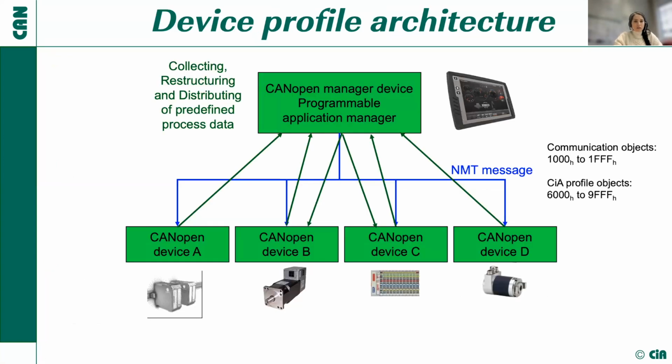And in this slide, actually, I would like to go more in detail about the device profile architecture. It is a system design concept that you can pre-define or pre-configure. Actually, it is better to say pre-configure your process data in the application manager and later collect them and distribute them to communicate with the devices, which are already predefined.